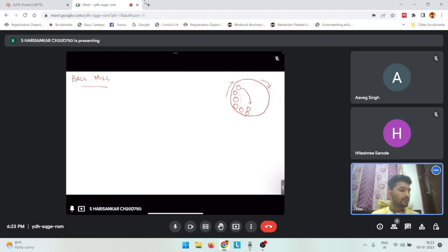Now when this falls back down to the bottom part, you have your feed also inside like this, and all these feeds will be sandwiched between these balls and will get crushed between these balls, and that is how size reduction occurs in a ball mill. So the main force or principle of size reduction in ball mill is impact, right?